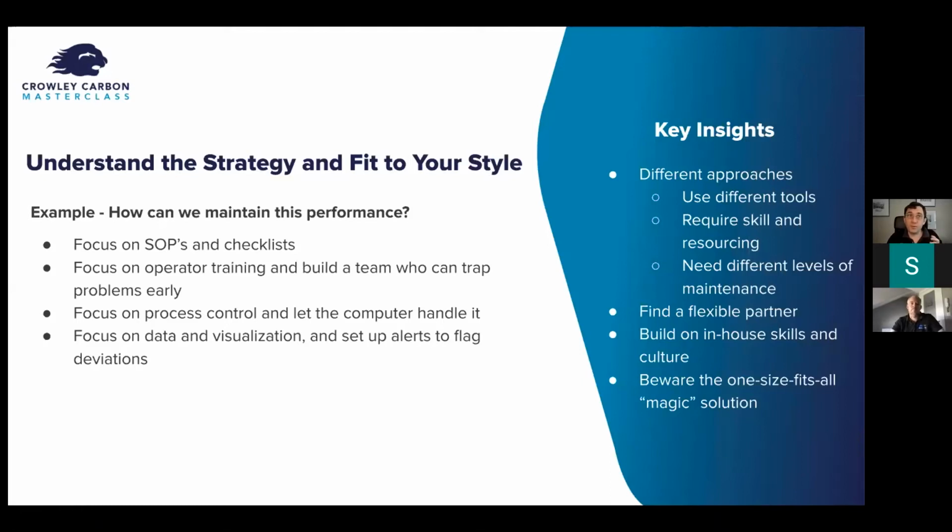So some people may focus on developing good standard operating procedures, good checklists to understand, if this happens, then do this, then this, then this. And if it all goes really badly wrong, call this person. Other people may focus on operator training. So you may go speak to a simulation vendor and they'll build you an operating trainer simulator, or they will help your team learn about the process. You maybe will develop an internal training program so that your operators and your junior engineers get good at spotting and identifying and tracking the problems early.